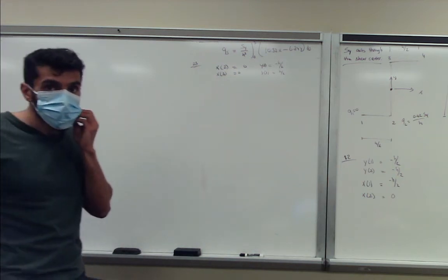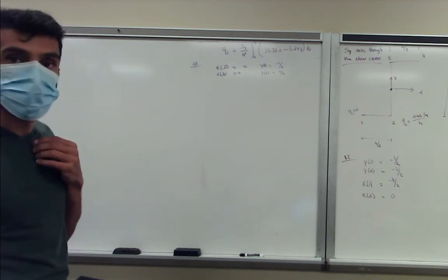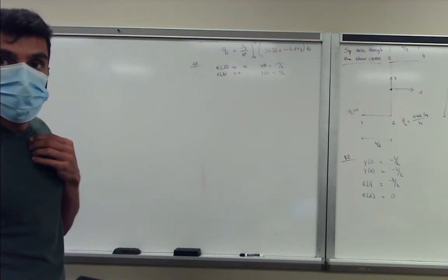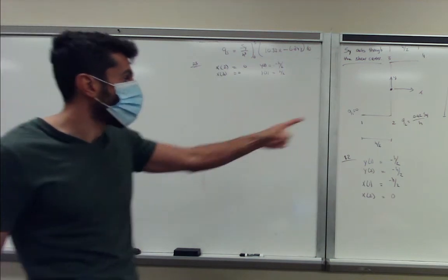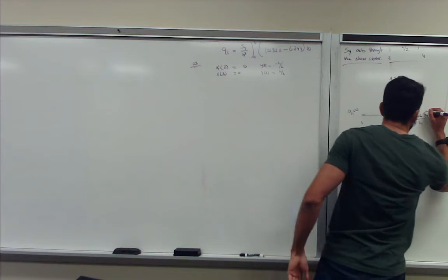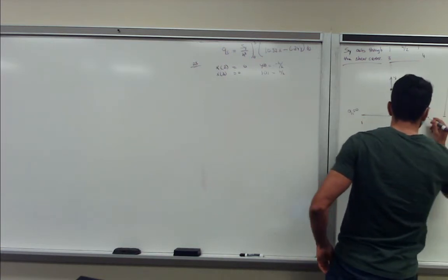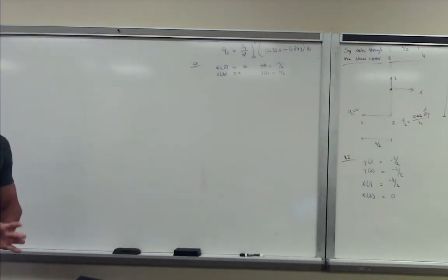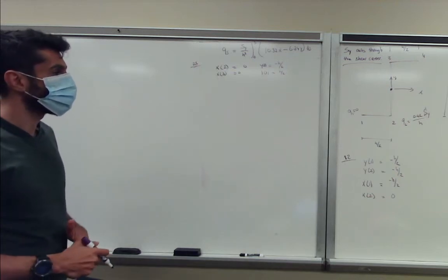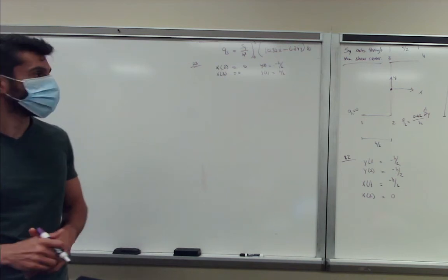Yes? I understand that Q1 is 0 because everything was 0. About Q2, it says 0.42 S1 or S12 over h, Sy. So this is a capital S. So capital S is the applied shear force. I understand the confusion: the lowercase s, the uppercase S, and then we have Q's that have one subscript and two subscripts.